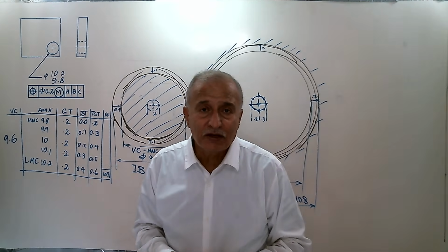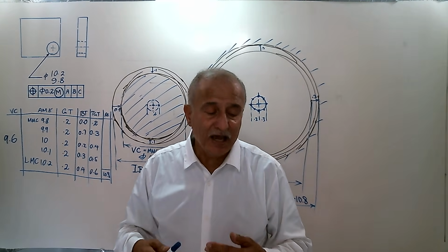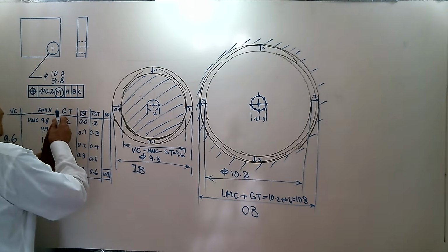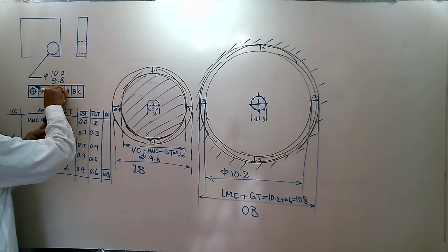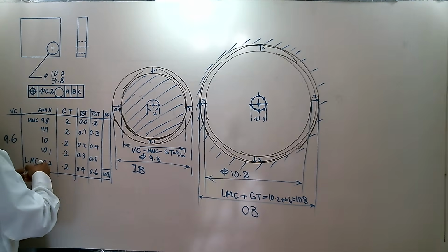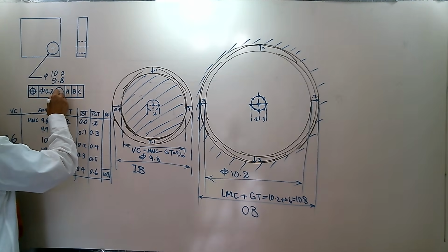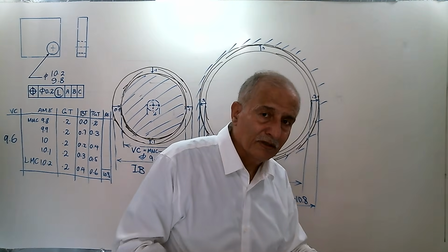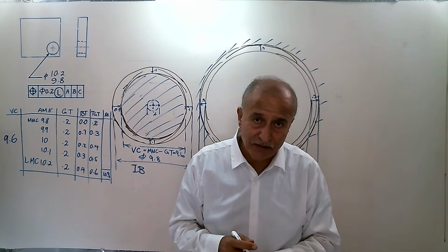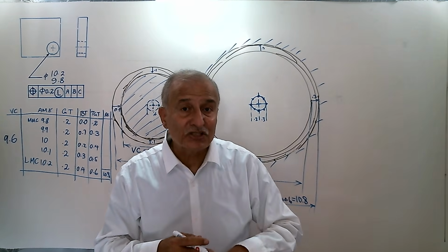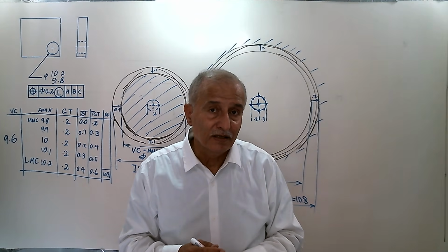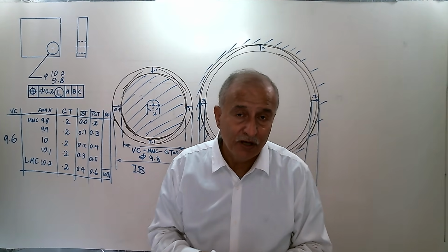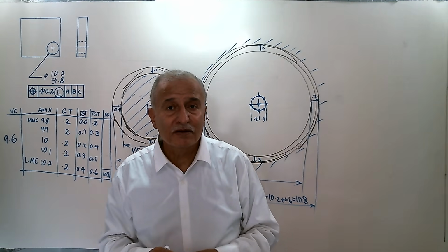Let's consider when we have a position tolerance at L modifier. What does it mean? I change M to L. What does it mean? First, rule number 1 does not apply. Even at LMC, you can have 0.2 error. This is the meaning of L modifier. Bonus tolerance is also permitted.